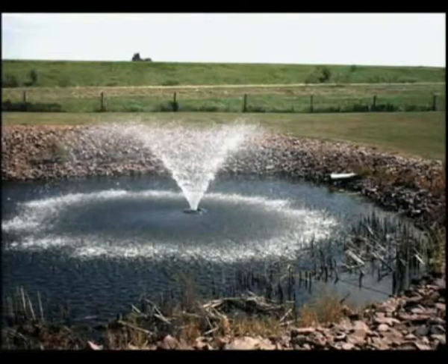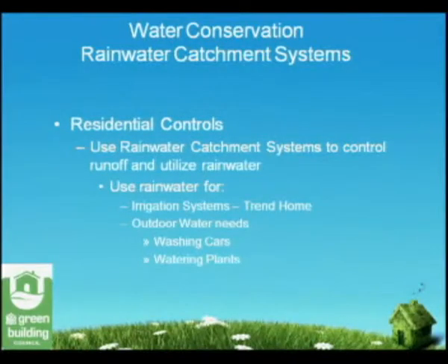So those rains that we had last June, these areas could potentially fill up and have to spill over. But for your other traditional rains, we have a better way of being able to keep this water on site, filtrate it through our soil so it gets clean and down to our aquifer. Another example again of a dry retention pond. You'll also see aerators in wet retention ponds. You'll see aeration within them to keep that scum from coming to the top and keep them nice and clean.